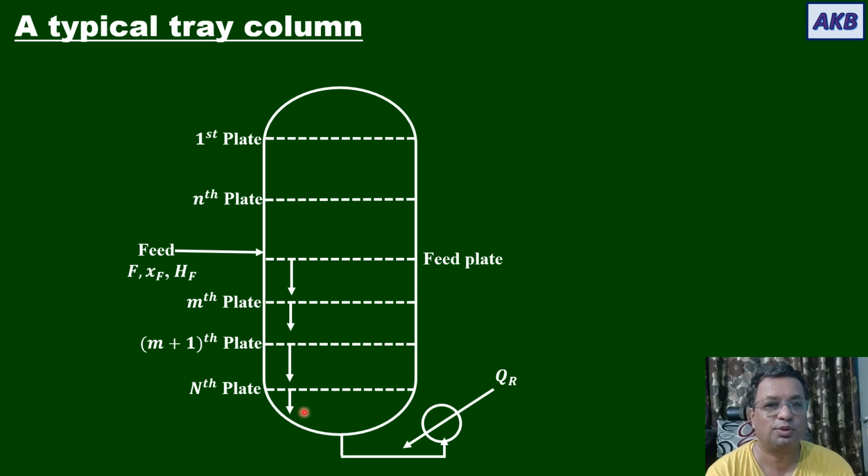The purpose of providing heat is to boil the liquid solution so as to create the vapor phase. Once the vapor phase is created, it is admitted at the bottom into the column, and the vapor phase then rises through the column.